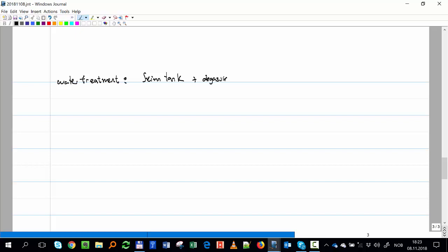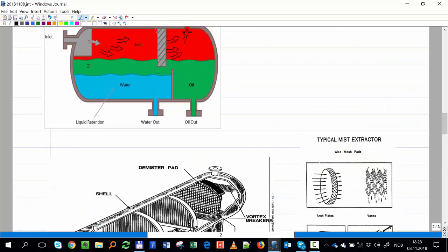We have to take out the gas that the fluid has, and this is the most common onshore, where I have space to put a big tank. It needs a big space, and it's very similar to the weir plate, where oil goes at the top and starts spilling out from the top.